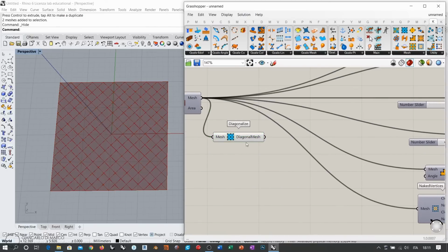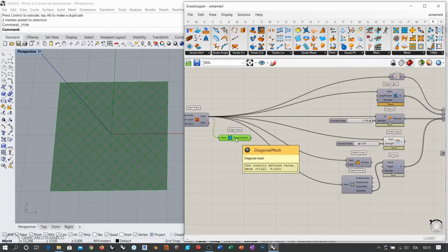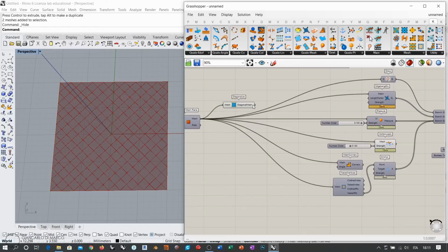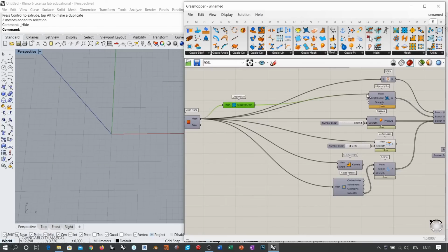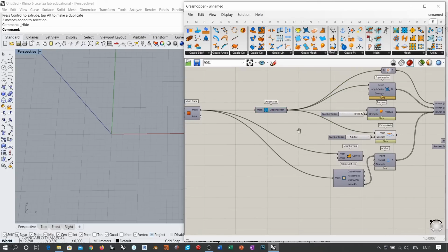So if you work with this diagonal mesh, the important thing is that if you consider the corner, as it is based on diagonals, the corner always has the diagonal edge with one endpoint in the corner point, which is an anchor point, and the opposite end is free to move. So if you work with this diagonal mesh, then you can produce a more regular deformation for your mesh. For example, if I substitute this diagonal mesh for the actual mesh that I want to deform, and I apply pressure and gravity to this diagonal mesh, and I visualize this diagonal mesh as well.